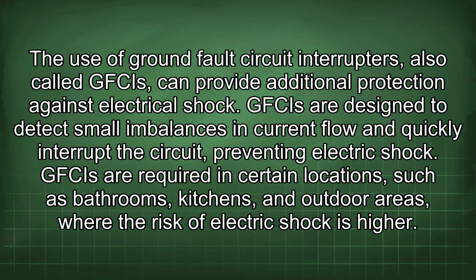The use of ground fault circuit interrupters, also called GFCIs, can provide additional protection against electrical shock. GFCIs are designed to detect small imbalances in current flow and quickly interrupt the circuit, preventing electric shock. GFCIs are required in certain locations, such as bathrooms, kitchens, and outdoor areas, where the risk of electric shock is higher.